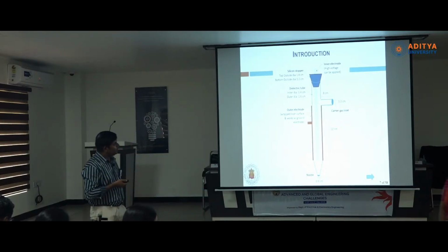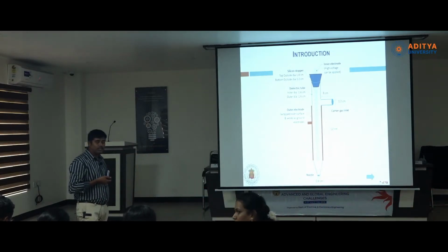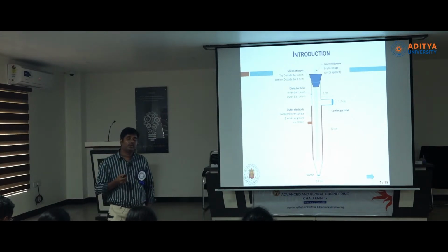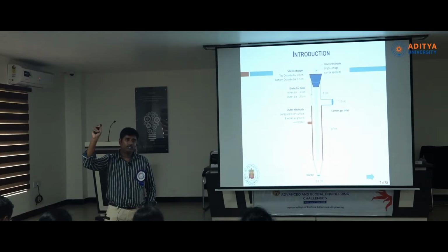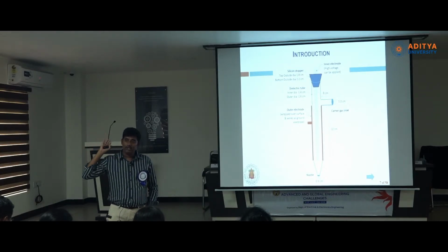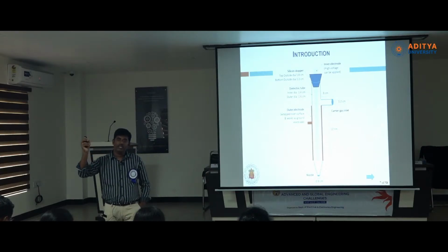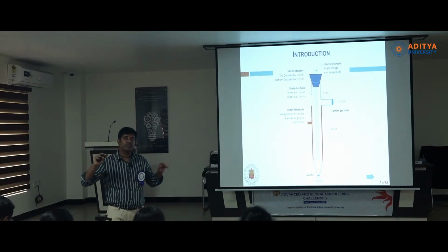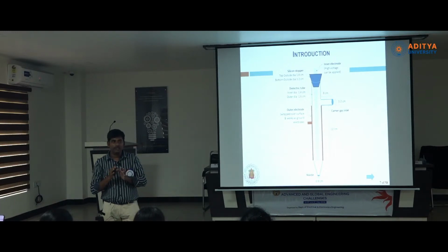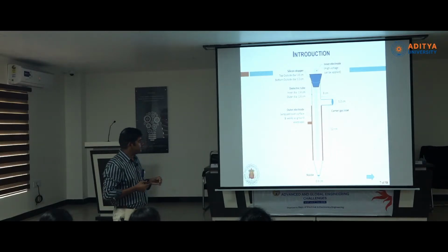So the same phenomenon we are using here, and not only here, you might have known about the electrostatic precipitator. In thermal power plants we have it for pollution control, isn't it? What is the phenomenon there? In the electrostatic precipitator we place negative electrodes, and the walls of the electrostatic precipitator are charged, and the gas is sent through the medium, a big room, let us say. So the gas itself is charged, and the negative particles will be attracted to the walls of the electrostatic precipitator. Later on you need to scrub it, right? So such technology we have.